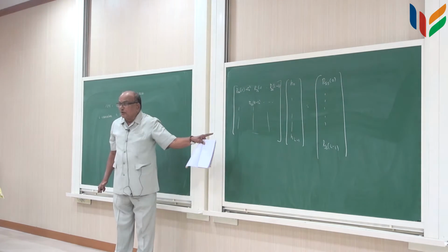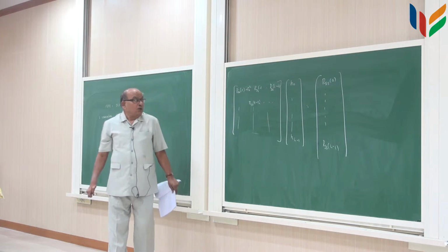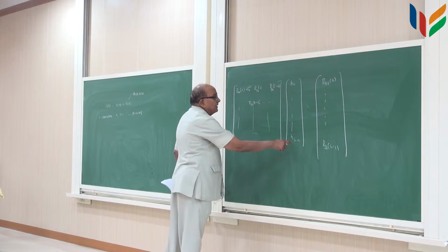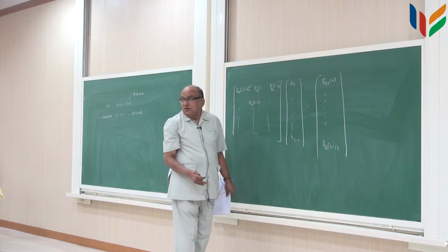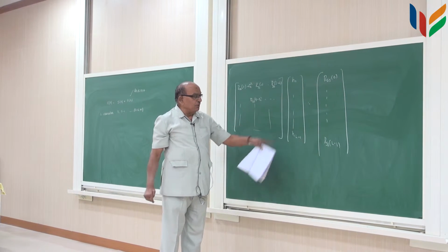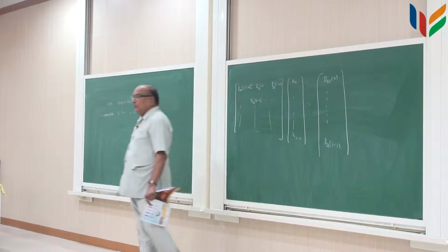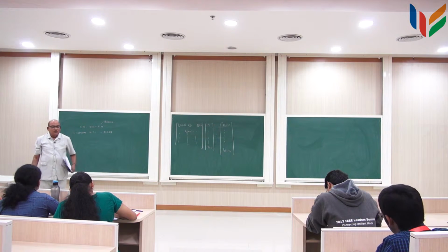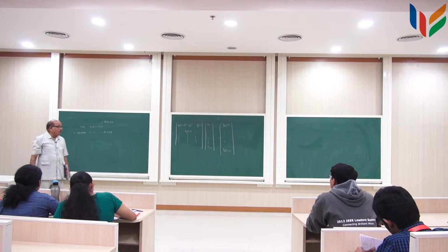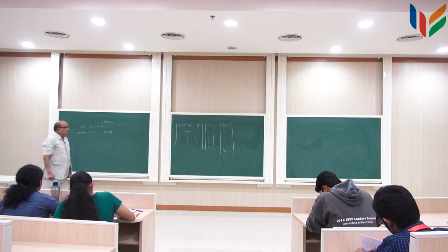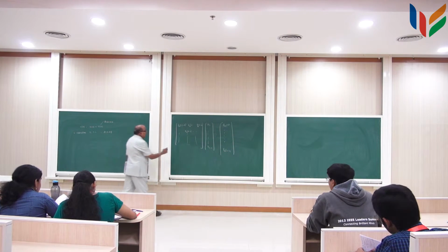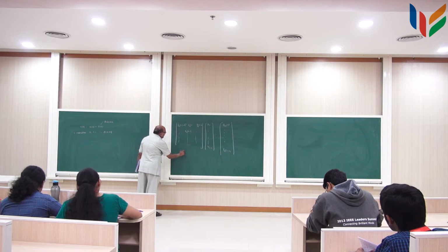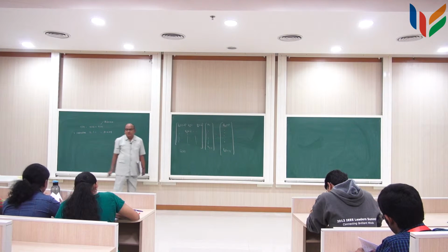This was where we ended up in the last class, right? So the H can be obtained by inverting this matrix. So you get H0, H1, H L minus 1, and so on and so forth. And that will be the discrete filter, which will give you the best estimate of S of n with minimum mean square error.